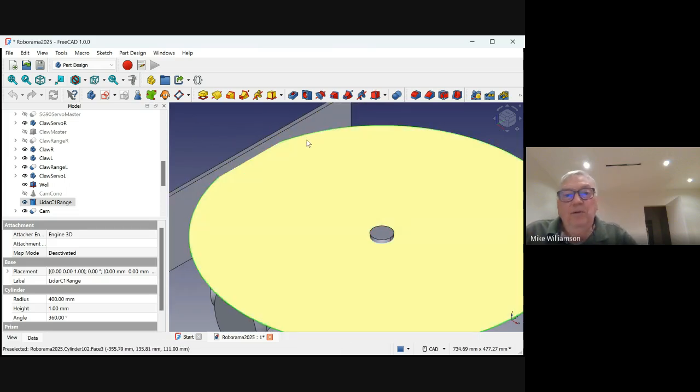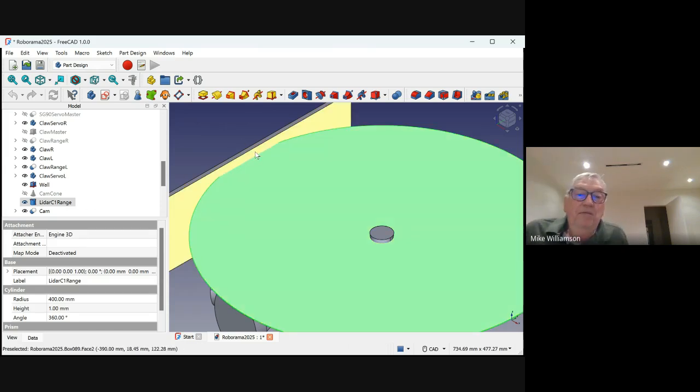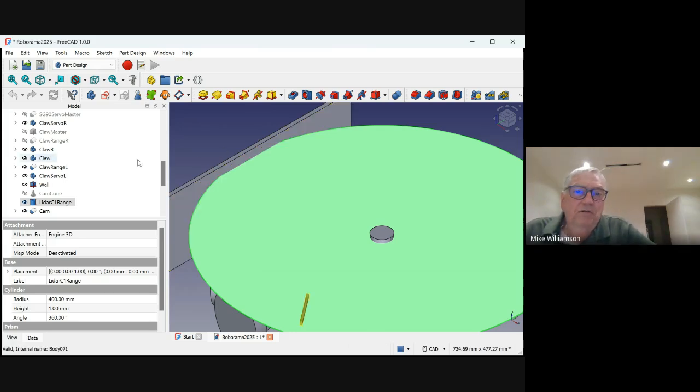So it's going to be my main odometry, just seeing the walls, where it's located, so that I always have good position and heading using the navigator. And the walls I'll have predetermined. I'm not using SLAM, it's just a map of the walls. Since it's a known size, you can do that easy.